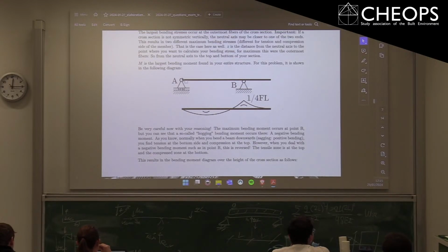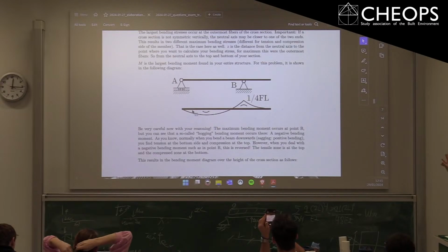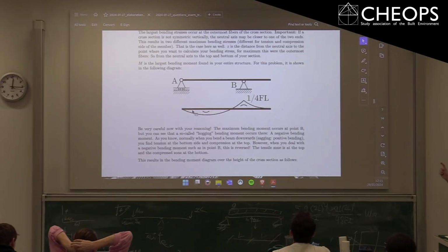But often if you have a continuous beam with a support that's, well, hinged to it, so you don't interrupt the beam, like it's not two parts, but like it's beneath it, you often have like this force that is pushing it upwards. And that's the cases where you often get like these hogging bending moments to the opposite direction. Does that make a bit sense? Yeah. And you can always like get these diagrams, right? So this is basic statics. Yeah, exactly. So if you're not sure intuitively about whether it's hogging or sagging bending moment, just calculate it for yourself.